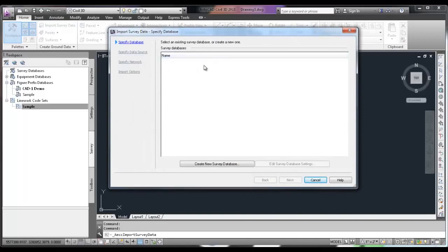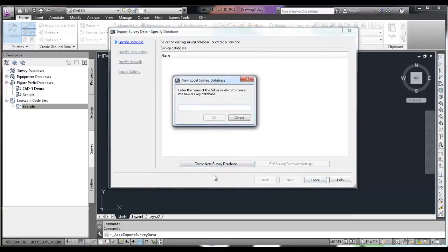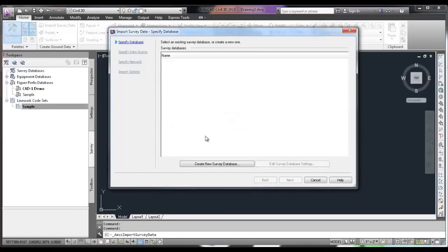It's going to ask me for the survey database. As you can see, I don't have any survey databases here, so I'm going to create a new survey database. All right, I'm going to give it a name. This is going to be my Field to Finish Demo Database. You'd give this your project name, something along those lines, right?